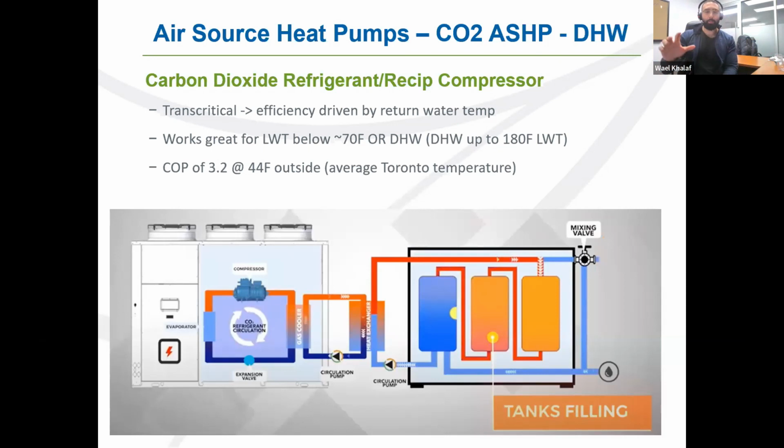But again, we want to create some sort of a stratified tank to have the hottest on one side and the coldest on the other side, so that the coldest water is what goes into the heat pump, thus creating the larger temperature differential, which is going to cause the heat pump to work in the most efficient manner. So again, whenever we get into heat pump applications for domestic hot water production, we really have to use a different approach to how we design our storage tanks.